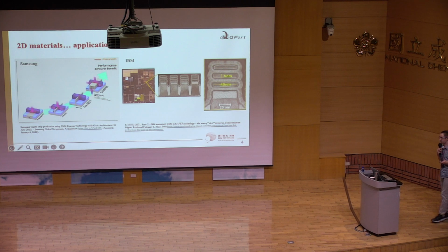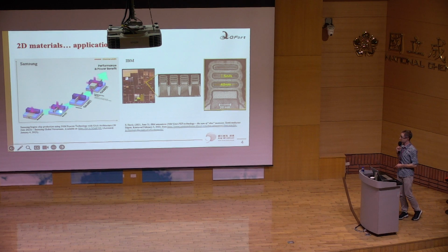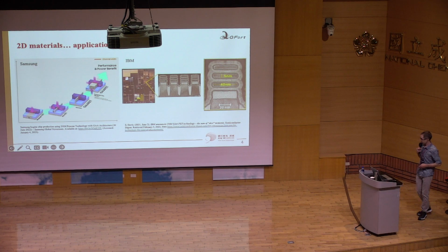If it's too narrow, you start to get leakage currents. And so that drove the development of different transistor designs, basically where you have a gate that wraps around your conducting channel, or you separate your conducting channel into different nanowires, or the latest developments, these nanosheet transistors.